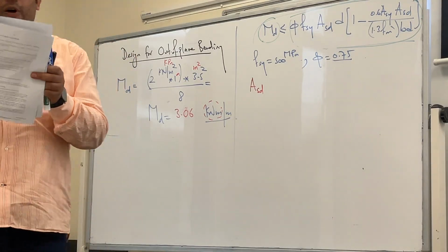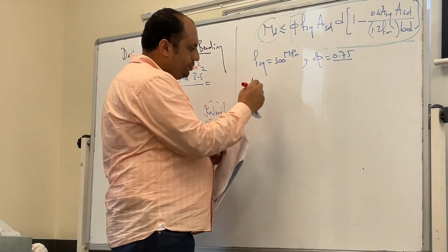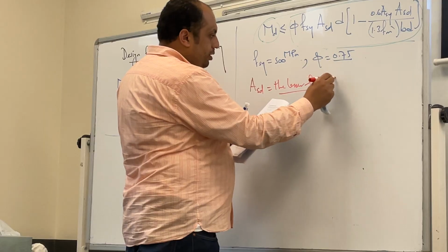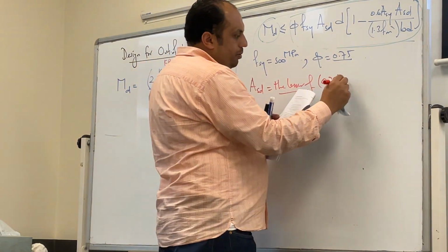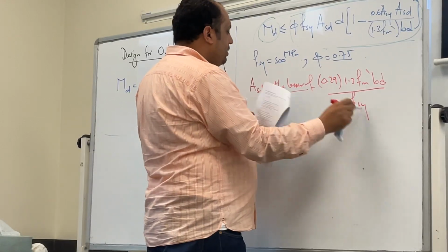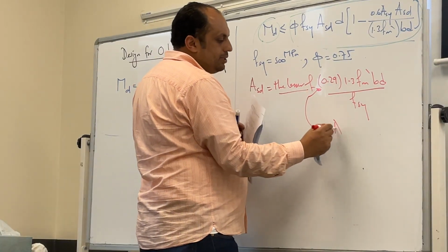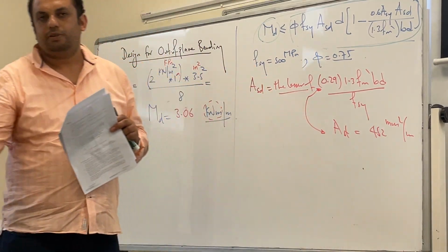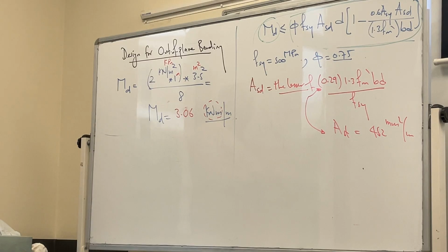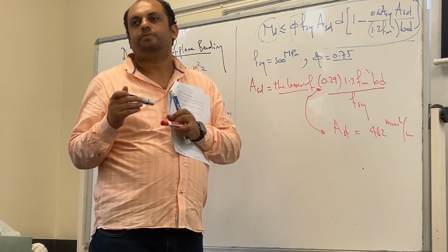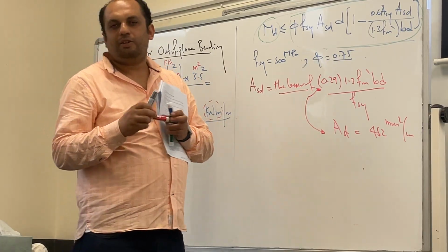The minimum of, or the lesser of, 2: 0.29 times 1.3 f'm b d divided by Fs yield, and AST. How much is AST? 452, right? Do we have the values on the top? What is B and what is D? I did mine per whole wall length, not per meter. You can divide by 12, the same anyway.